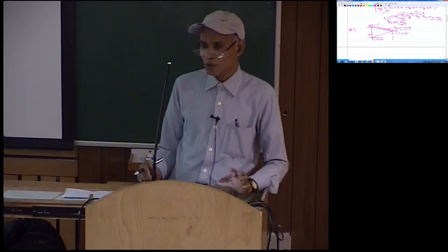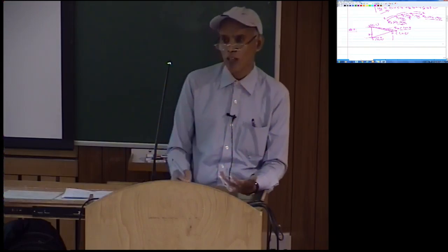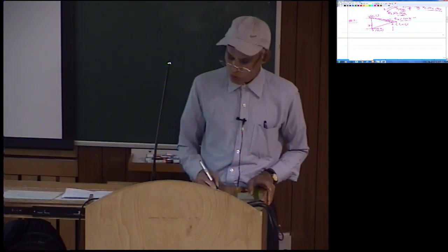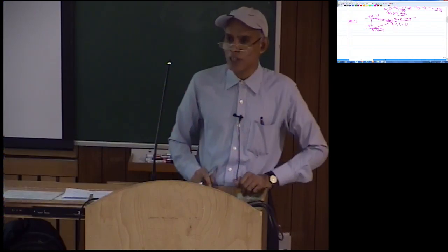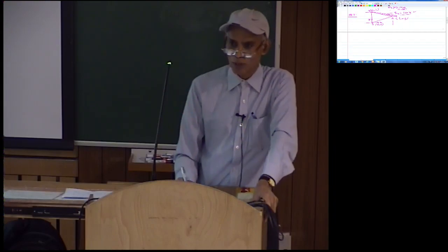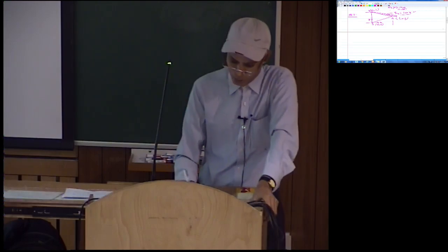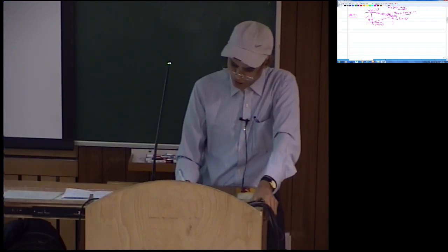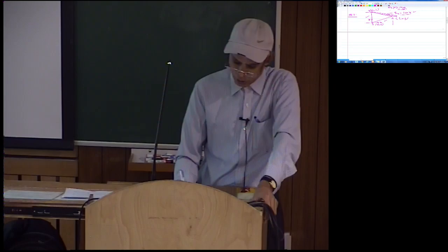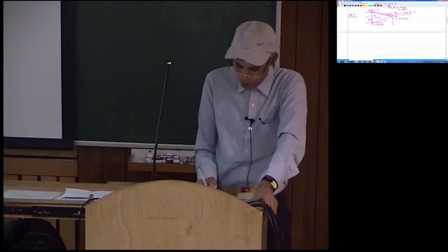2D problem. So 2D means the load is in the in-plane direction, in the plane containing the structure, so it can be a plane stress or a plane strain. So when you talk of a load vector due to this distributed force on an edge, you will have to consider a 2D problem, not a 1D problem. Some of you just took it as a 1D problem with only one displacement component along the x direction and tried to work out the load vector, which is not correct, because the two dimensions are comparable, and the load is acting only in this direction. So you obviously expect that it will of course stretch in this direction, and it will also have some displacement in this direction. That is what I expected.